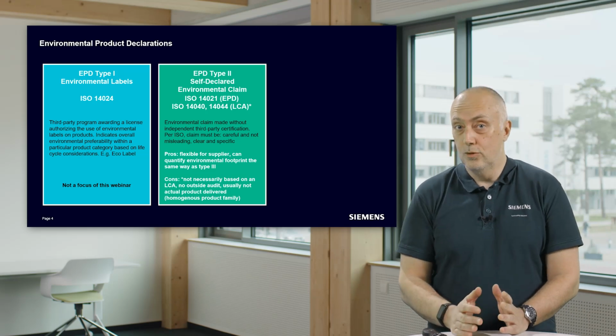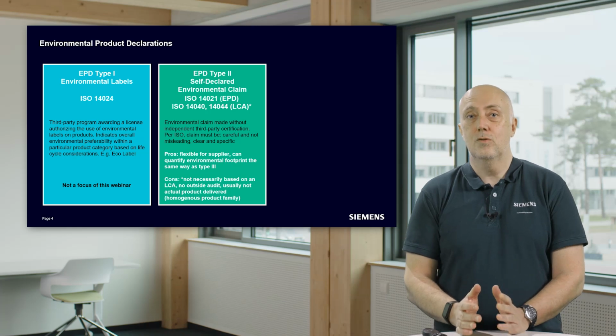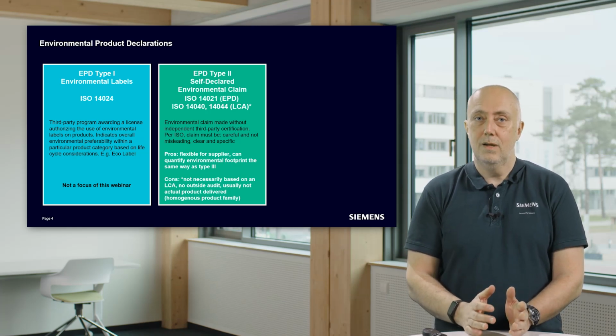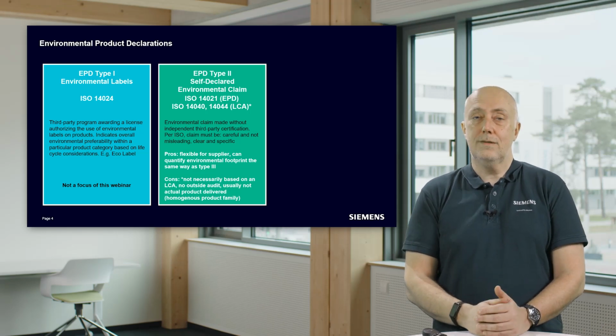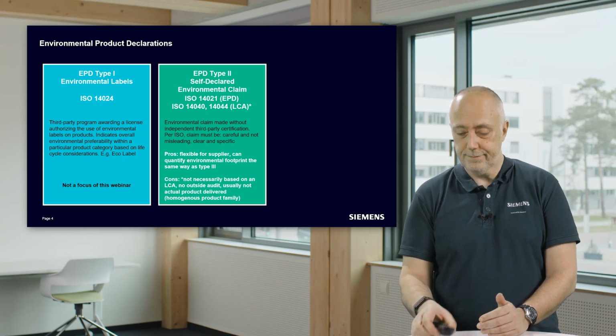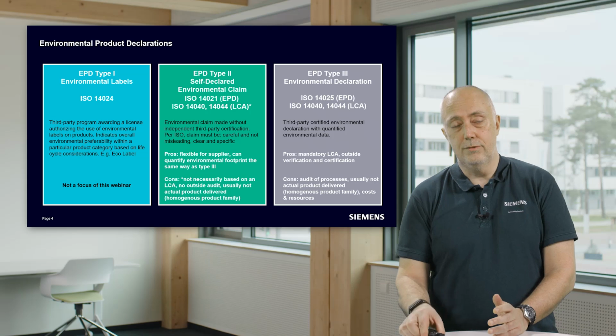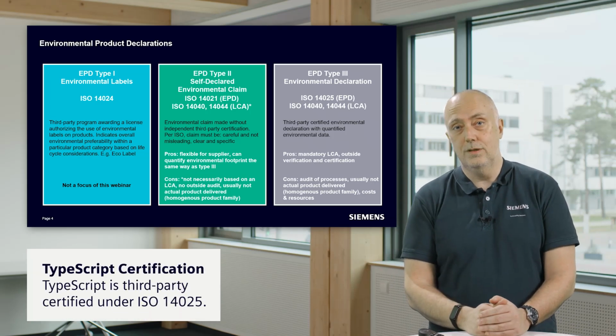But it is important to note that because the product is not the same, the emissions also won't be exactly the same as the product you will purchase. And this is true not only for EPD type 2, but also for our last type of EPD on the list, type 3 EPDs. So I mentioned type 3 EPDs already a few times here, and type 3 EPDs are third-party certified.